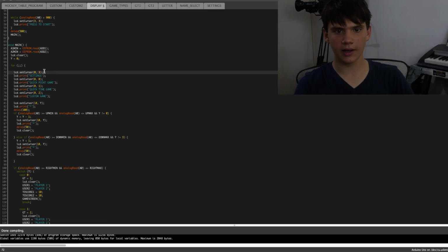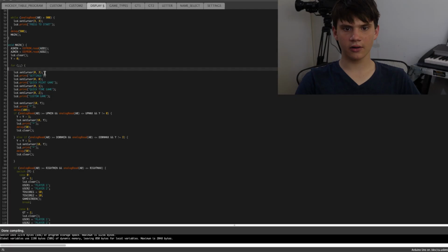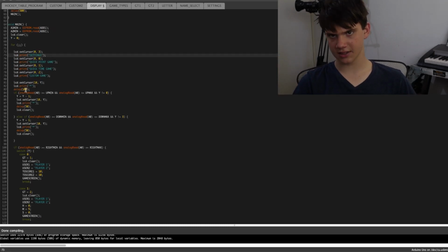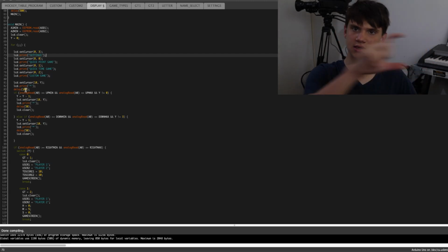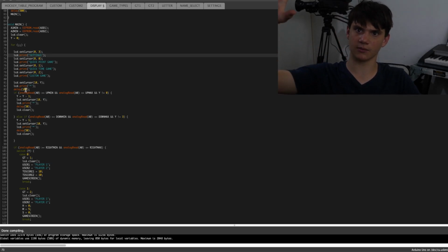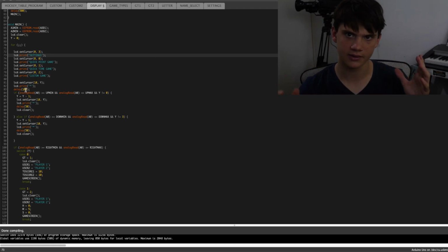While it is in this loop, lcd.setCursor 0, 3, print settings. Now this is the actual menu system you saw in the video. So I'll go ahead and play that again for you. And now it goes ahead and lists all of this. And then it goes ahead and lcd.setCursor 18, y. This is where y comes in. Y is 0 and 18 is the x-axis. So it goes 18 characters across and then 0, which is the top line. And then it goes ahead and prints an asterisk. This is how you can select where you want to go and how you navigate the menu system.